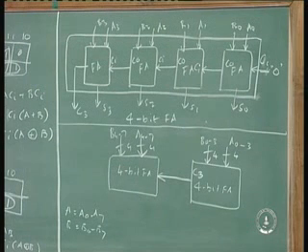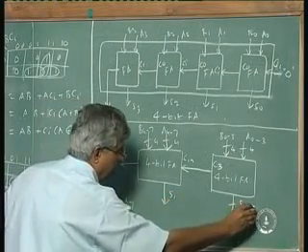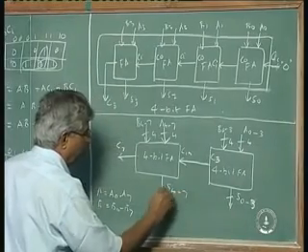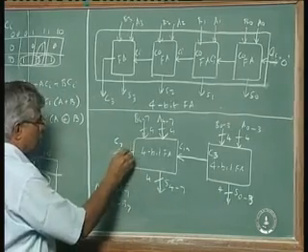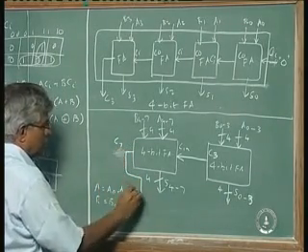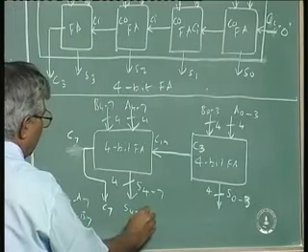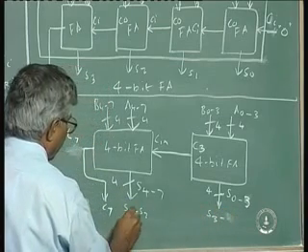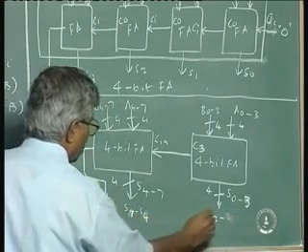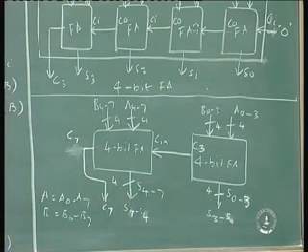So this should be sum 0 to 3, 4 bits, 4 to 7, 4 bits. So this is 4, this is 4. So 4 bits, 4 bits. C7. So C7, S4 to S7, S0 to S3. If you want to write S7 to S4, S3 to S0. First 4 bits, second 4 bits, the last bit is the carry bit, is the 9th bit.